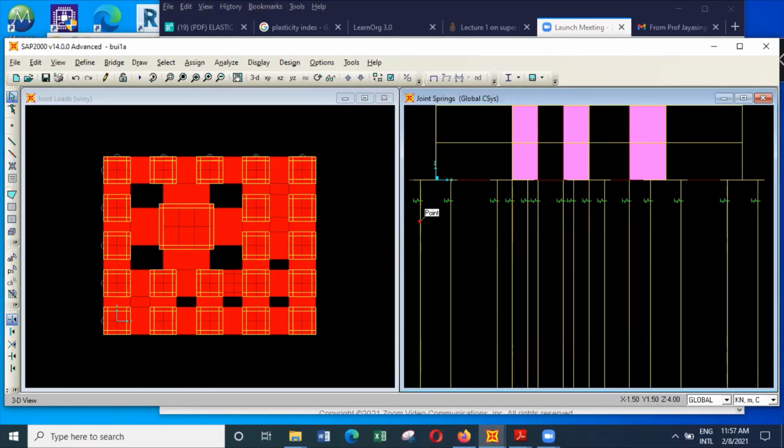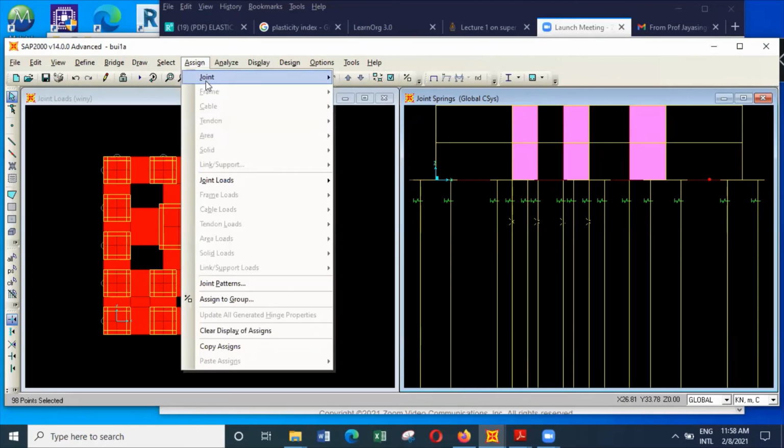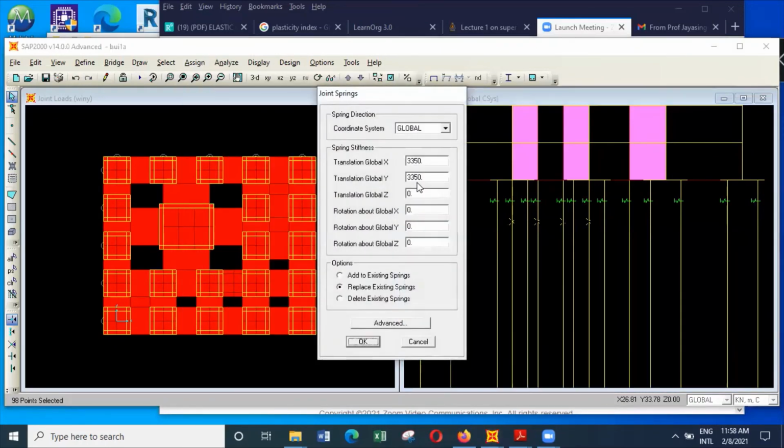So what we do is, we can add those two and divide it by 2, take the average value, and then multiply it by 2 again to represent the height. When you select the spring here, in this area it's 1675, this area 10,800. So over this height of 2 meters, I have to allocate the average value. So I'll allocate an average value of 12,475.